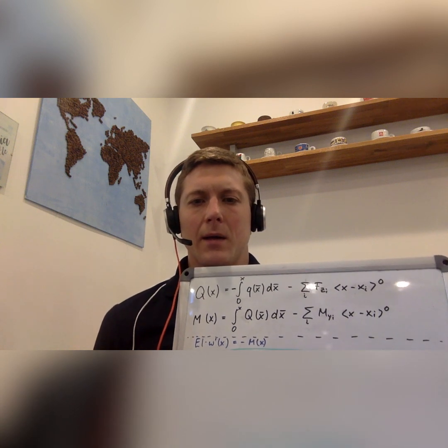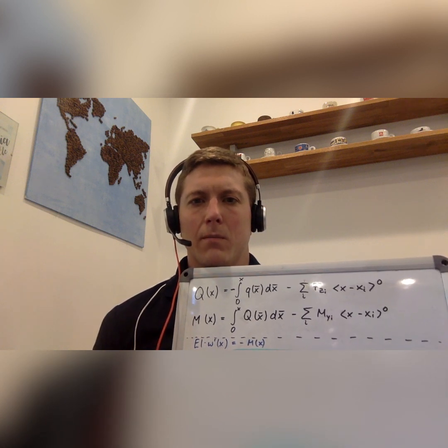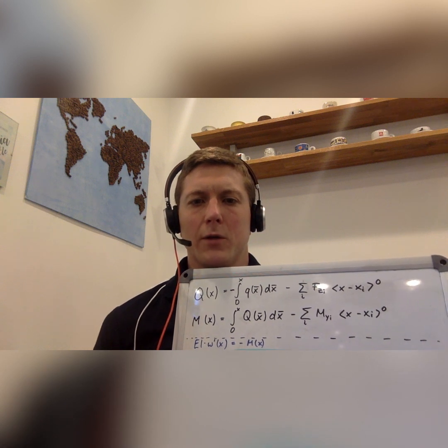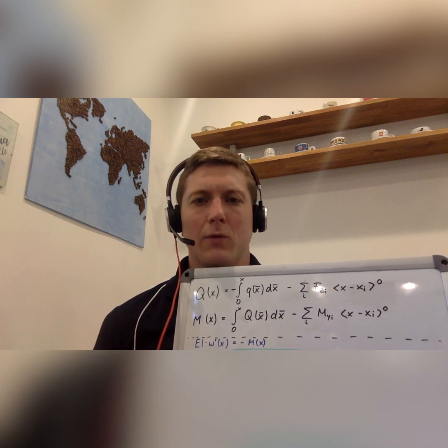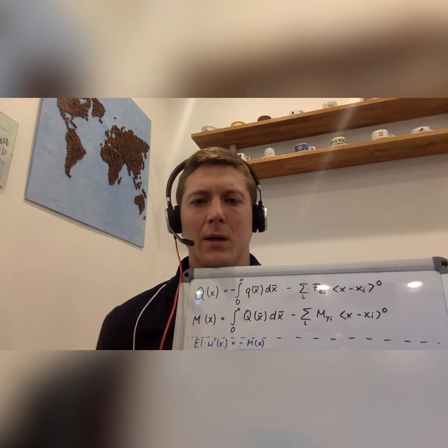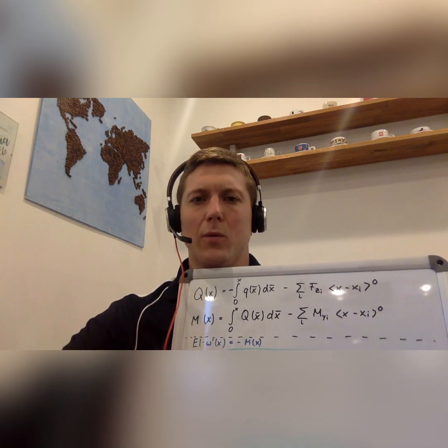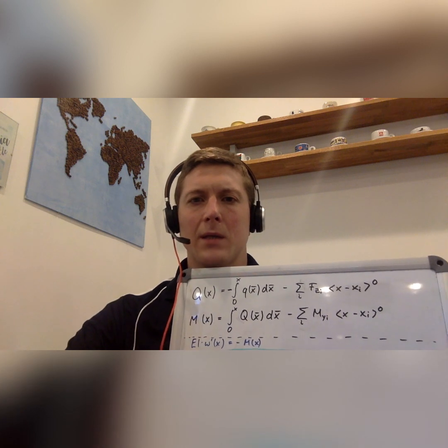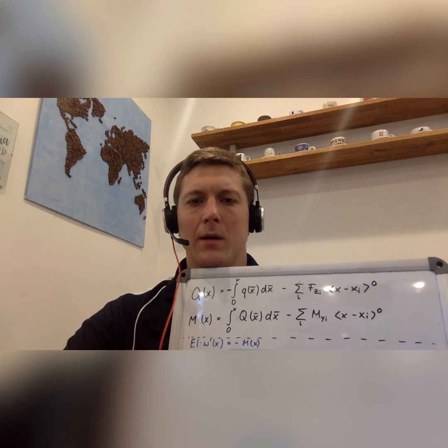And this I, this is the variable we already determined. It is the area moment of inertia, in this case with respect to the y-axis, as we only apply a bending moment with respect to the y-axis. So this was our last topic we were talking about. We said that the area alone is not enough to determine some resistance against the bending moment, but it's how the mass elements are distributed over the cross-section area, and this is described by this I, the area moment of inertia.